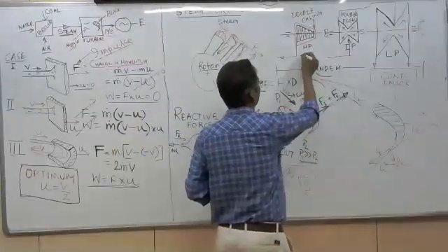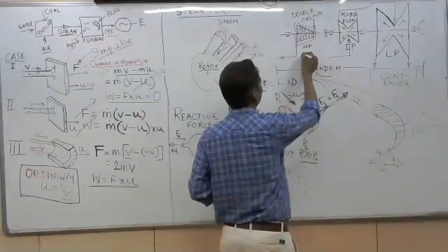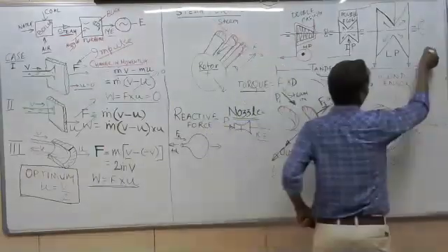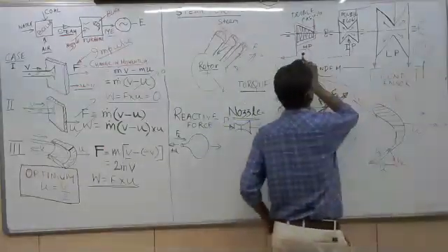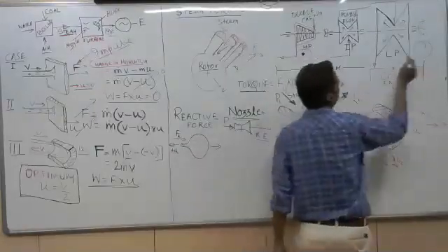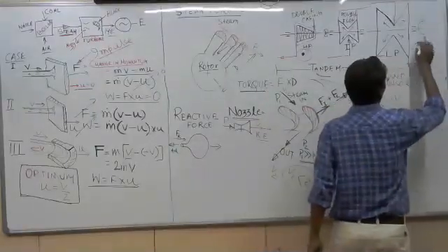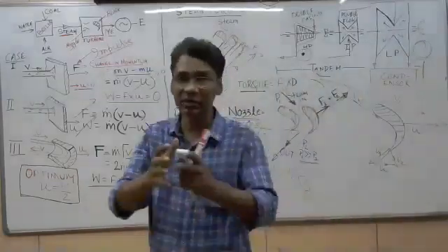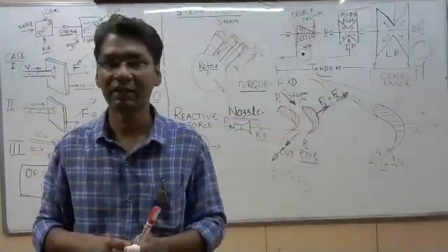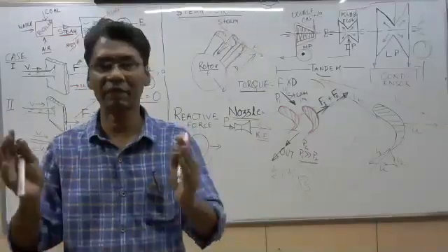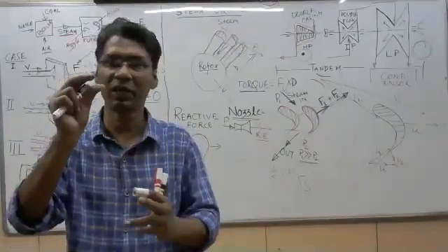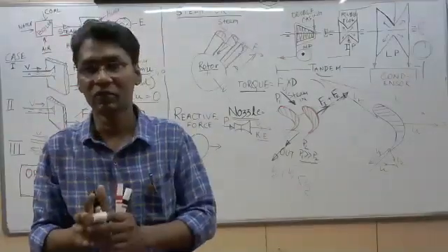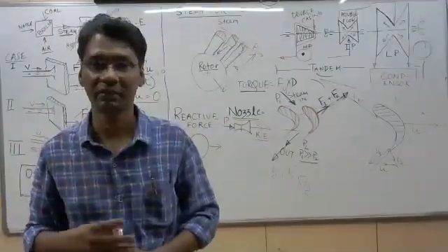At high pressure, the same amount of steam has a volume like this. If the pressure reduces, the volume becomes this much for the same amount. So 1 gram of steam over here has a volume like this, and a larger size is required to accommodate it. As the pressure reduces, the volume increases. Do you understand? Suppose there is 1 gram of air, you compress it, it will look like this. If you release the pressure, it will occupy a larger size. That is why the low pressure turbine is larger.